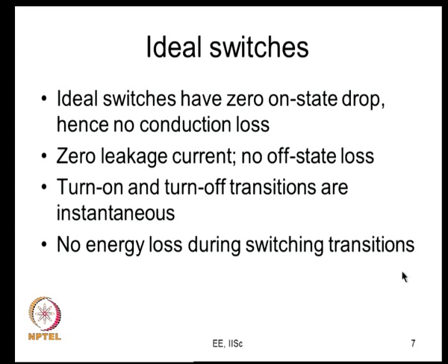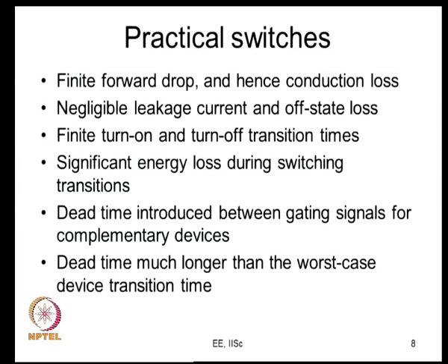So, this is what it is ideally, but in a practical case you say that it is a finite forward drop and hence there is conduction loss. We discussed this conduction loss in one of the previous lectures. There is negligible leakage current and no off state loss. We did not discuss off state loss at all, because in most power electronic devices the leakage current is quite negligible. It has finite turn on and turn off transition times.